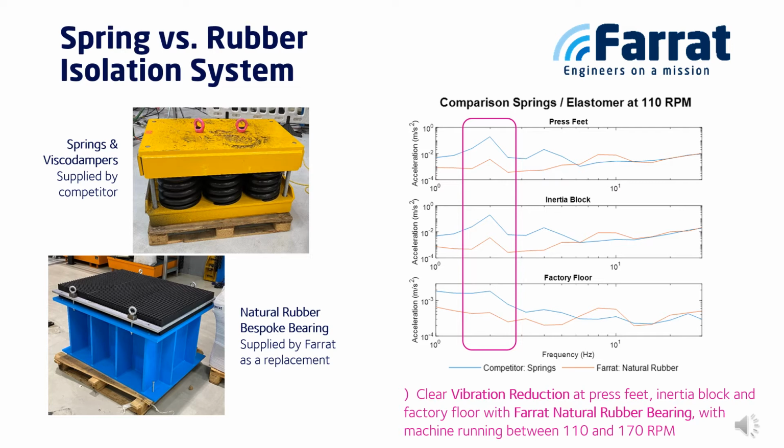These results demonstrate that the client's requirements have been met. The Farrat isolation solution has significantly lowered the movements of the machine whilst maintaining a quiet environment for the neighbouring buildings. This proves the efficiency of Farrat rubber isolation systems for this type of application, where bespoke design solutions are needed to solve complex engineering challenges. On the other hand, springs with visco dampers have proven unsuitable because of their very low natural frequency, dangerously close to the disturbing frequencies generated by the presses and increasing the risk of facing resonance issues.